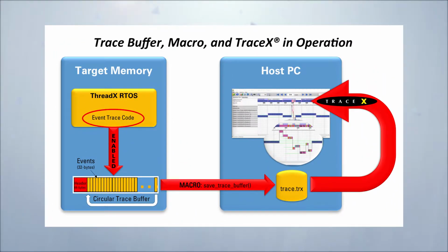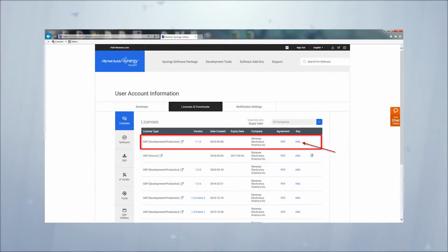ExpressLogic's TraceX is an application external from e2studio used to map operations inside of the ThreadX RTOS. TraceX will utilize a specific type of memory dump to show this information, and this requires that you enable this feature in the project's configuration. One important note is that you will require the use of a production license for this to work, as you will need to have the ThreadX and other modules source code as part of your application.